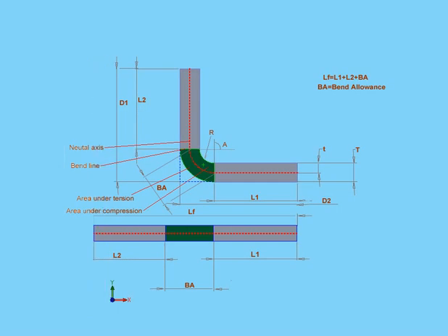You can input your data manually into a matrix of the bend angle and bend radius. If you're not sure of the bend allowance value, you can run some tests. You need a piece of the exact same sheet metal you're using to manufacture your part, and then you'd bend it using the exact processes that you'll be using during your machining. Just take some measurements before and after the bending, and then based on this information, you can adjust the bend allowance as needed. Another method that SolidWorks uses is the bend deduction method.